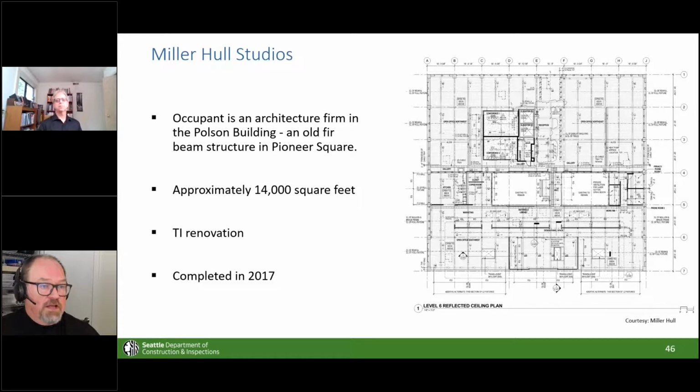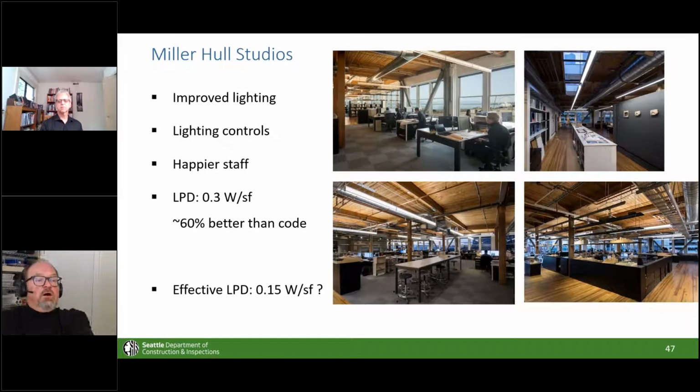Yep. The original lighting for it was all linear fluorescent. It had been done in the late 80s. And basically, for the time, it actually was pretty okay, right? It was fluorescent. It was, I think, 1.14 watts per square foot, which for the day was actually quite good. It was indirect direct. The biggest problem with it was that it had precisely one control zone. You walked onto the floor, you wanted to do some work, you were one person there on a Sunday, the entire floor plate had to be lighted up.